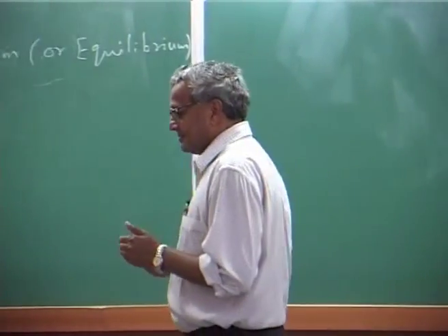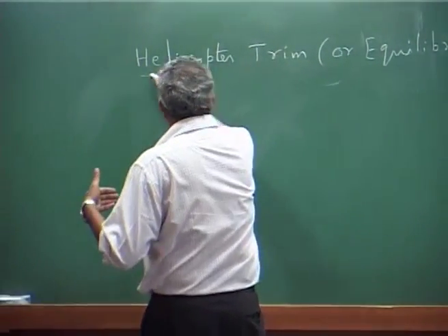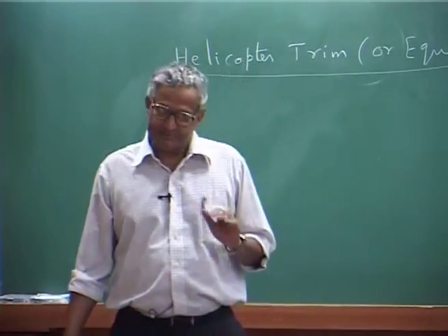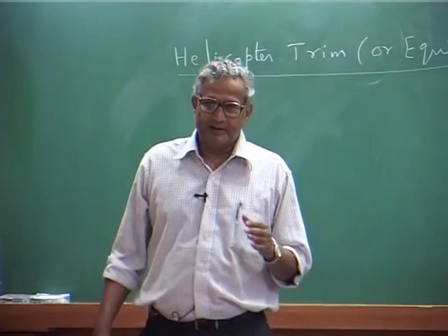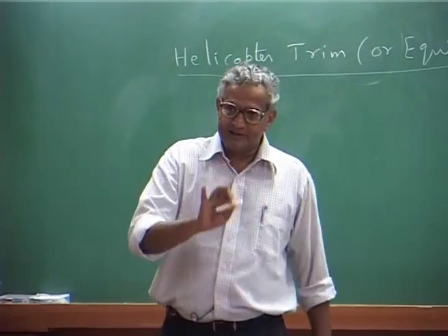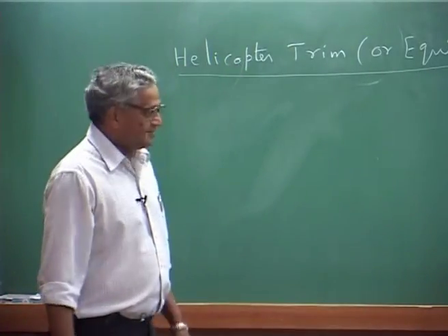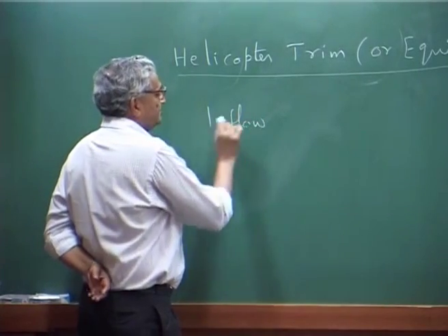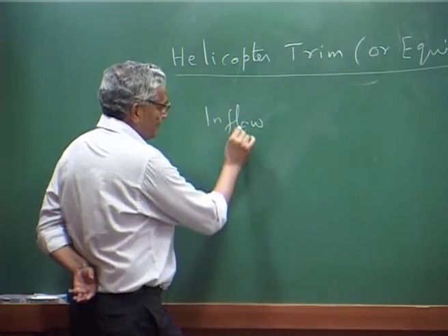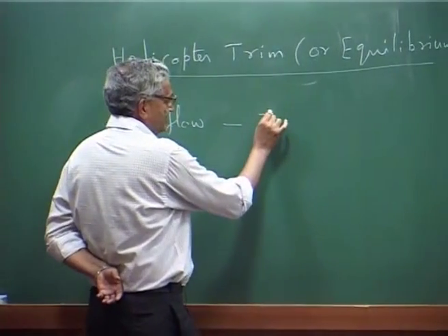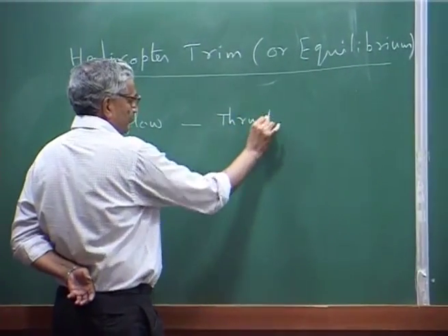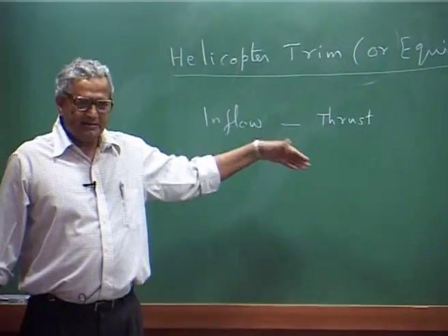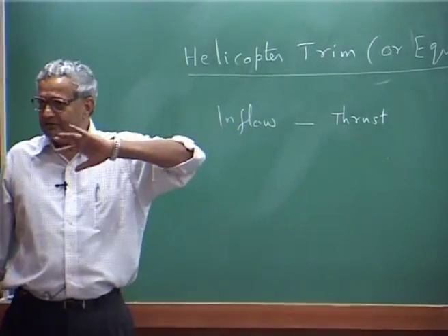Now, for that, pilot input will be evaluated theoretically. How will you get the trim from what we have learnt till now? We have learnt inflow first, and then inflow was related to thrust. This is one equation, rotor inflow. Of course, thrust is the key. You have forward flight condition, attitude, everything is there.